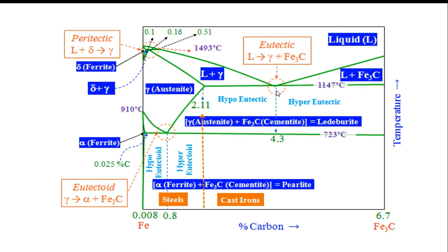Below that carbon percentage is called hypo, above is hyper. So here also you have hypo and hyper. And how to identify those phases: alpha, delta, austenite, cementite, pearlite. Those are the regions. After finding those, you have to find out the mechanical properties behind those phases and the temperatures. That is the importance of knowing. So that is the total content behind the phase diagrams, about the iron carbon phase diagram I already mentioned.